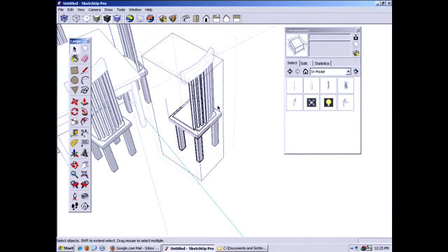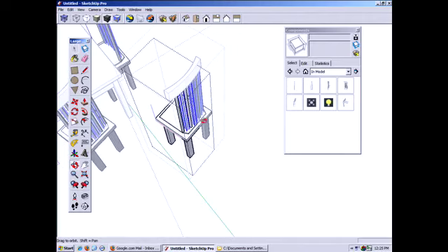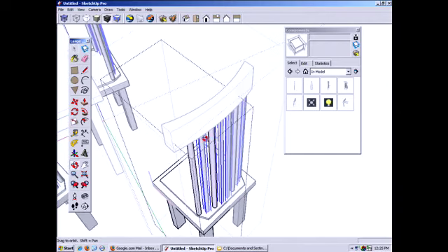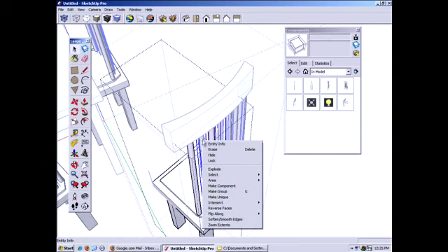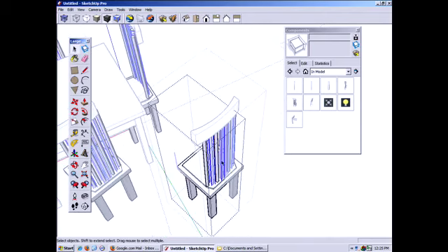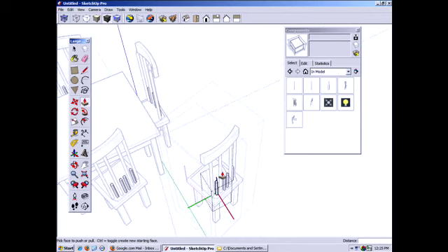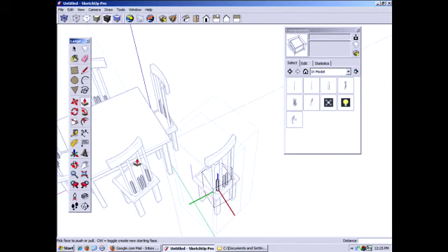How that will work is within the nesting. Let's say we take this and this slat and we make them unique. You do that by selecting them, right click, and we say make unique. You might have seen a little, now have a new component over here, that makes those unique. But because we're editing this and because we built it in, if we edit those now, that's going to happen around here too. So we've made them unique in every instance that we included them in. Does that make sense? Okay.